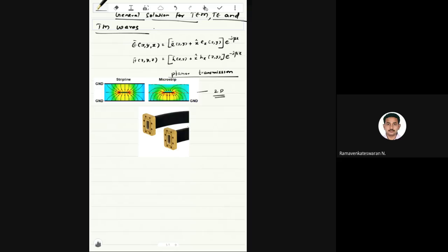However, we don't see them extensively in the syllabus, but they can be easily analyzed with the concepts learned in transmission lines. The strip line basically has two plates, on the top and bottom. There are two metal plates called the ground plane, and inside there is one conductor, again metal, usually copper. It's placed exactly in the middle of the two metal plates.